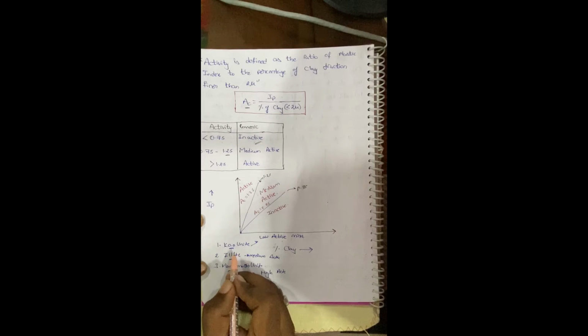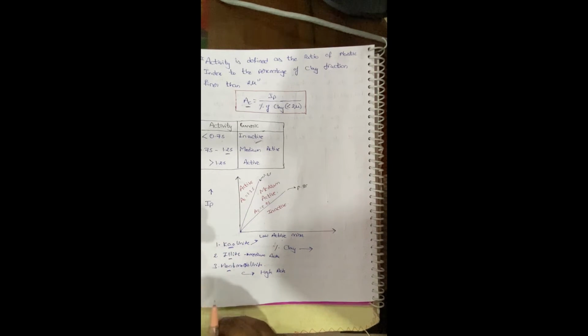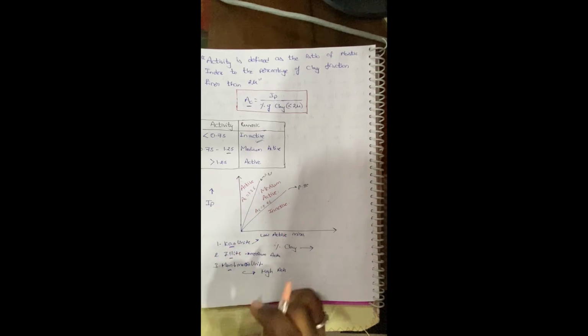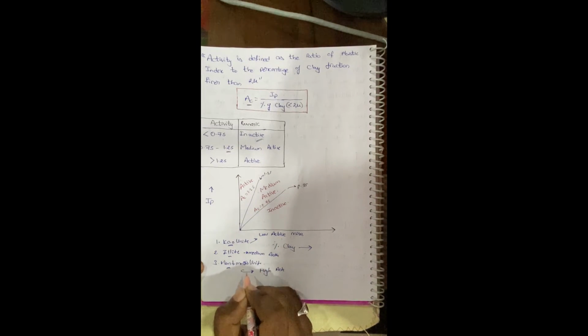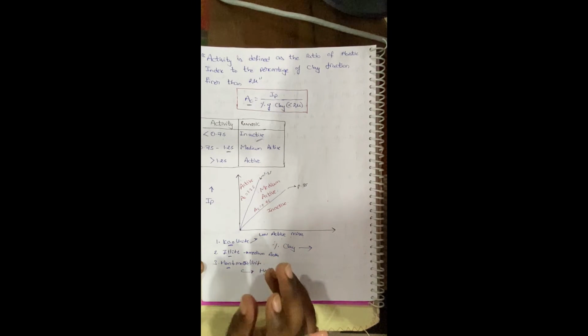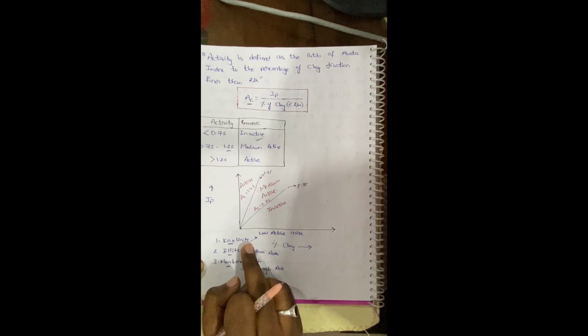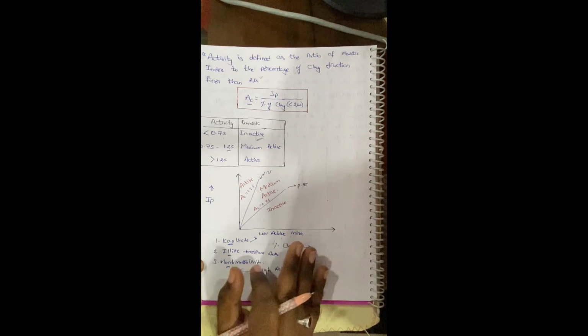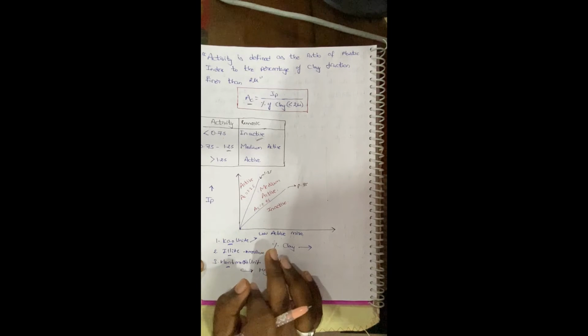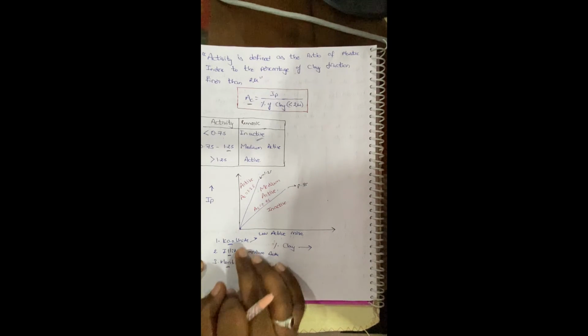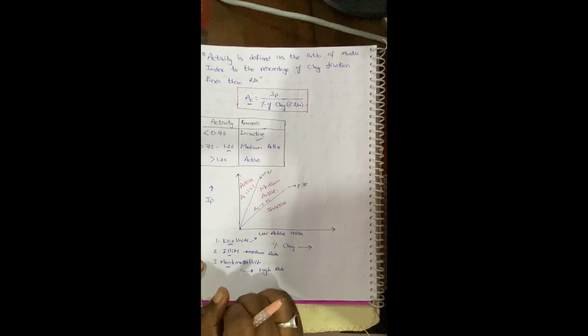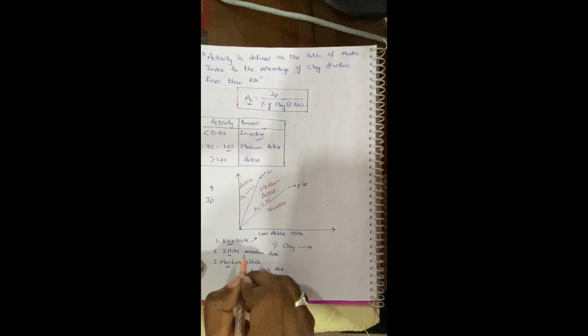Based upon the quantity of kaolinite, illite or montmorillonite, the composition of a soil is altered. So if the soil has montmorillonite, it shows high swelling nature. The volumetric change would be high for montmorillonite. Whereas coming to kaolinite, the volumetric change will be very low. So it doesn't show any type of swelling, the volumetric change in kaolinite. This is because of the structure in the